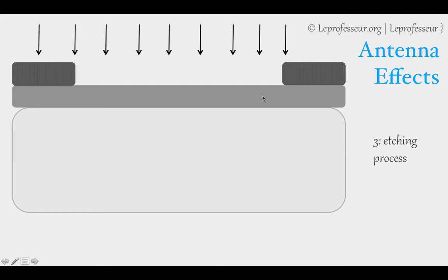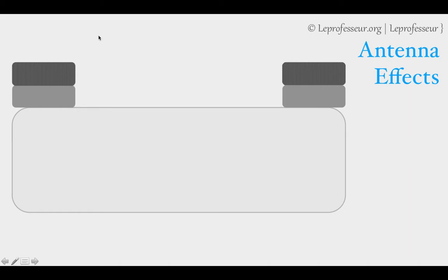And then simply the etching process. Typically this is UV, ultraviolet rays, or other processes, depending upon the foundry. After the etching, you can see that the oxide layer has been taken off from the substrate at the selected portion where your mask was not there.